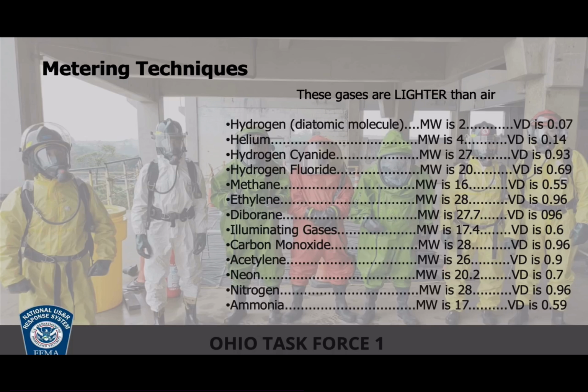And gas metering had been done for HF and for our 5 gas sensors. But right next to where the HF was leaking was this, and this gas was much heavier than air. So it wasn't until the entry team put the meter all the way down to the ground, at the base of the rail car where it had met the ground where it had derailed, that they found a flammable environment. So if hot work had to be done, like welding on a removal cap or a removal stinger for the HF product, and that had not been done at that ground base, you could have easily agitated that environment, moved that area of explosive vapor to its LEL right around where you're working and caused an explosion.